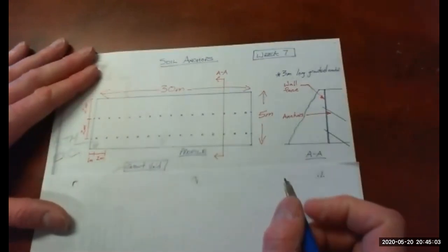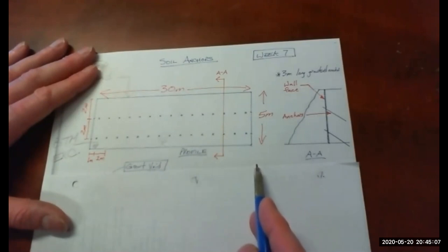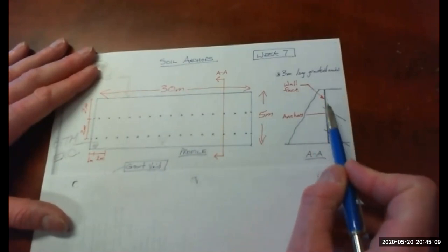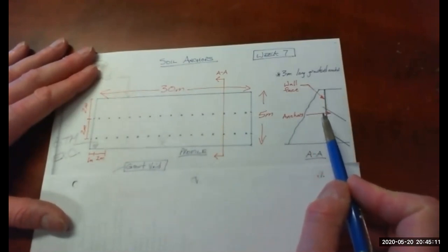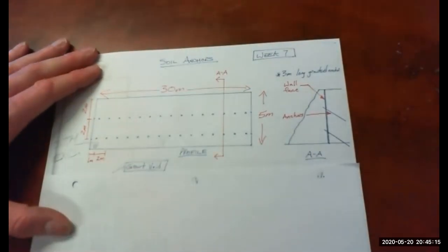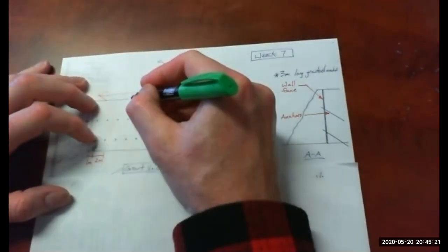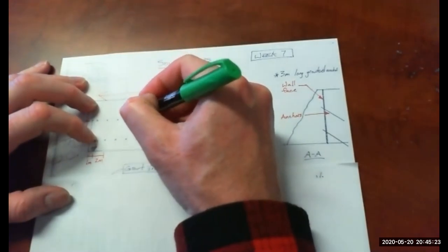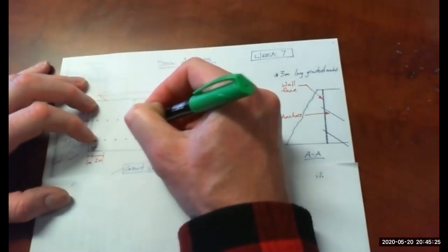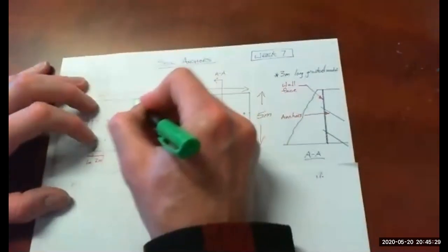The way the phased excavation works is, after you've done that bulk excavation, you need to come in and do pockets of excavation for the anchors. So how does that look? Let me draw it with colors here so that it shows up well. So you would come in and excavate something like this.